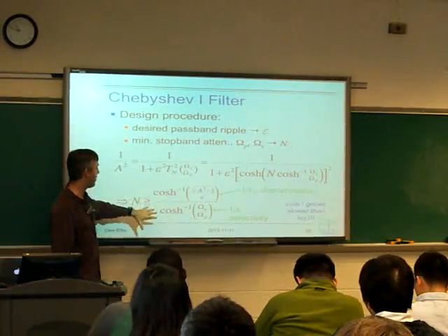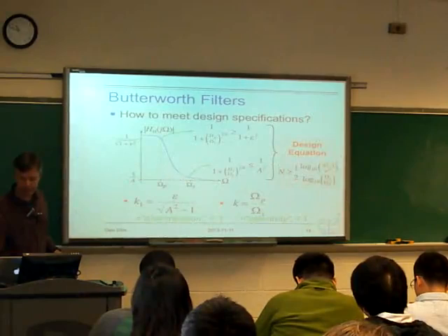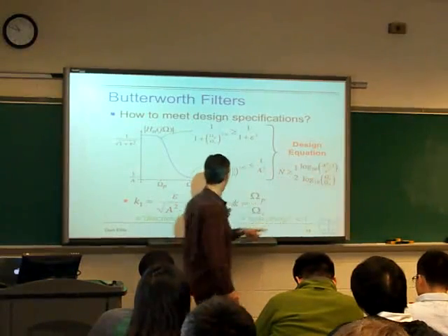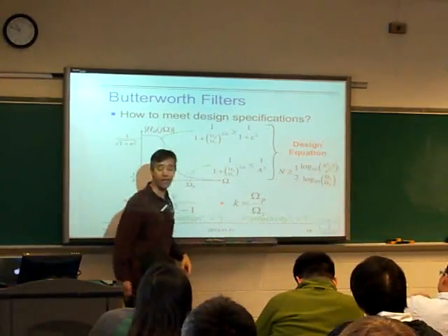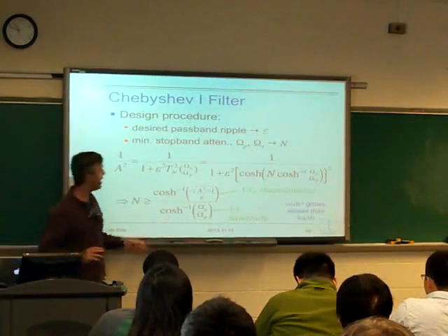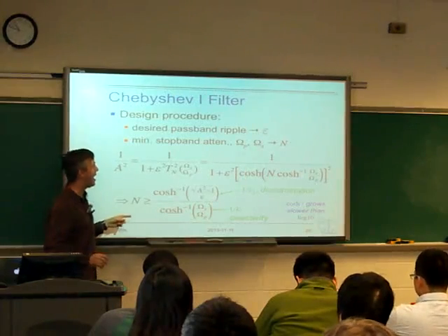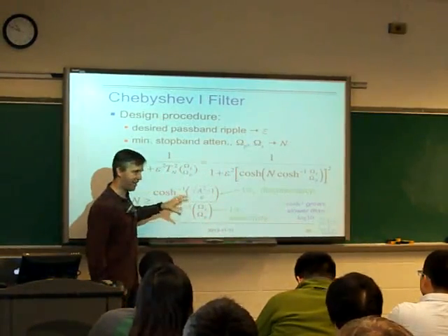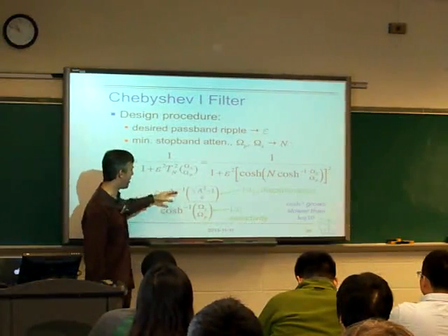Now, this equation here looks a lot like, if we look back to the analysis for Butterworth, this was kind of like that. It was the log 10 of this thing, which is the inverse discrimination, divided by the log 10 of this thing, which is the so-called selectivity. But here, instead of log 10, it's inverse hyperbolic cosine. And the point about that is that it's the ratio of these things, so the absolute values don't make any sense. It's not half of that. But it's the ratio of these two things.